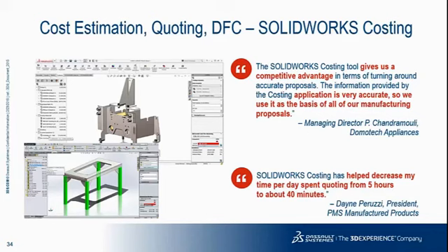I had one customer who went as radical as to get away from using extrusions, and he went to doing his frames from sheet metal, right? So he's able to get the material faster because everybody has sheet metal in stock, and he's able to make basically a unibody. Think of cars used to be on frames, right, and now they're unibody designs. He was actually able to make his machine cheaper, lighter, and actually more rigid, amazingly enough. So look at some of these alternatives and look at how much it's costing you. Make sure you're hitting your cost target. SOLIDWORKS Costing can help you out.